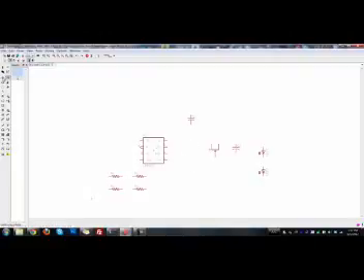So let's go ahead and get everything kind of hooked up here. We'll set up the LEDs up here. So we'll get LED 1 up there, a current limiting resistor for it. Let's grab this one, and again we'll use rotation. So rotate it, place it right there, and then we'll get another LED, stick it here, and then get another current limiting resistor.